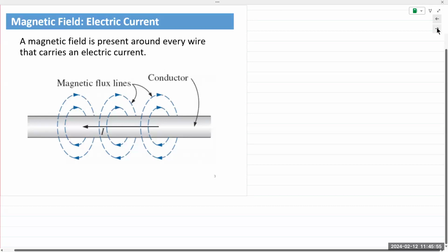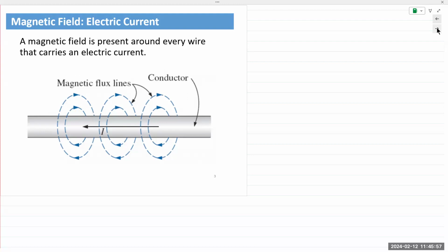If you have a wire or a conductor, it inherently has inductance, resistance, and capacitance. Any wire has a certain amount of resistance, a certain amount of inductance, and a certain amount of capacitance. It's an inherent property. For example, consider resistance and take a 100-foot extension cable, a power cord, like the orange ones that we see. You plug it into a wall. If you expect 120 volts at the power outlet, you would expect to see 120 volts 100 feet away.